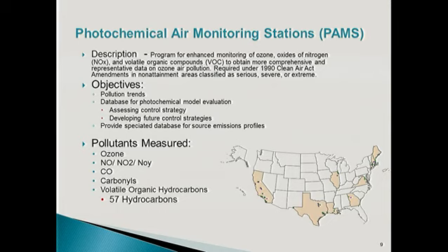Focusing on the ozone questions, the Photochemical Assessment Monitoring Stations, or PAMS program, was developed. That is basically looking at the different components, VOCs and NOx, and the formation of ozone. So part of this program is looking at a large array, namely 57 components of hydrocarbons, also with some carbonyl species, as different components to look against, like source emission inventories, to better understand each of the districts that are in serious non-attainment or above, to further their understanding of what's in their district to address their ozone formation.